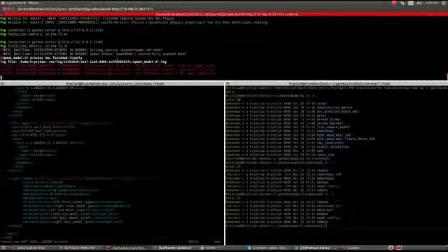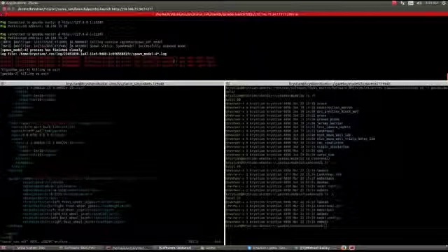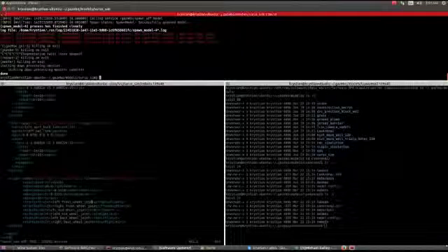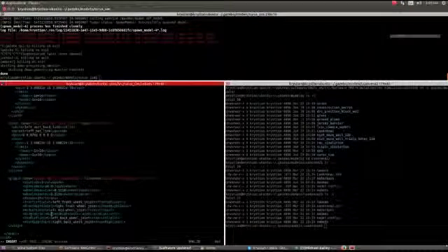Okay, so we need to make sure. Yeah, Michael, you're going to have to edit this part here. Let me just figure this out real quick. I actually named this incorrectly, and I named it simply mid-wheel joint when it should be the right mid-wheel joint. But just for the sake of getting this to work for now, the mid-wheel joint is going to be the joint for the mid-right joint. Since it's a 6-wheel differential drive plugin, we need to specify the wheel joints for the front, middle, and rear wheels.